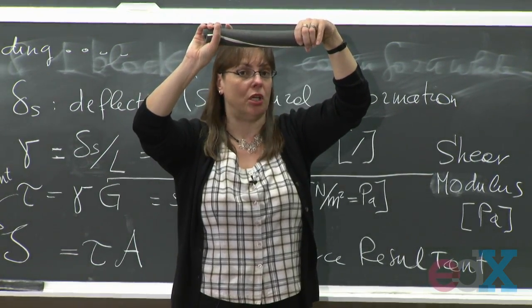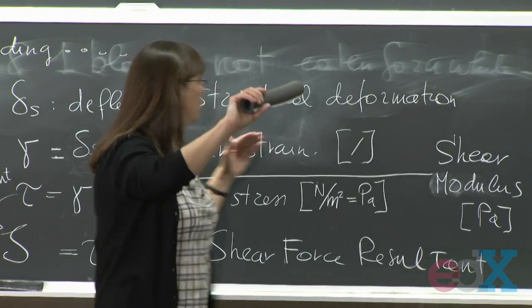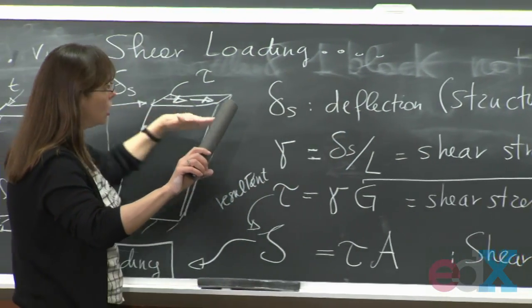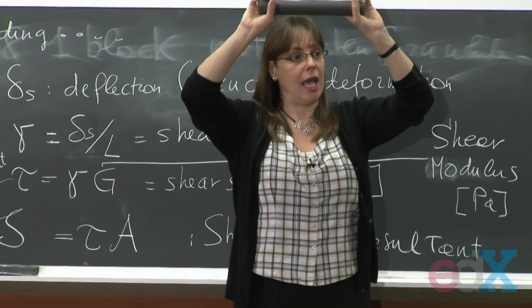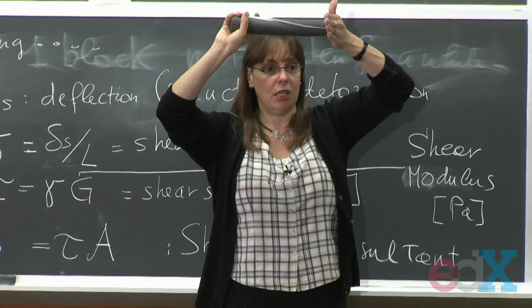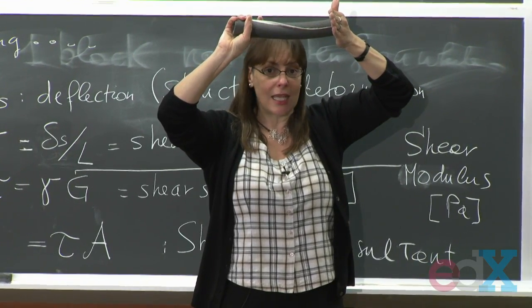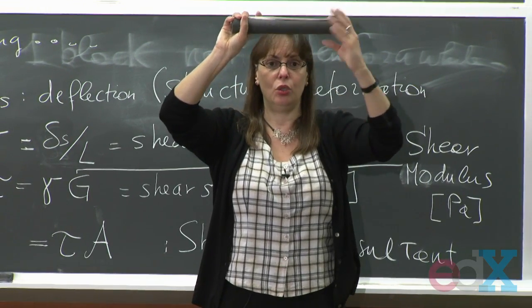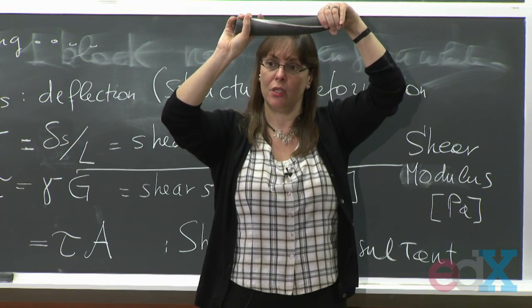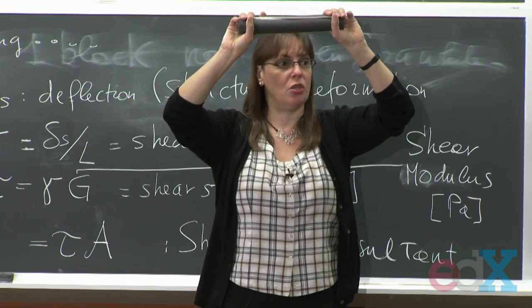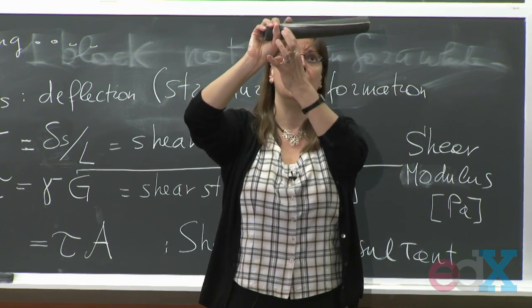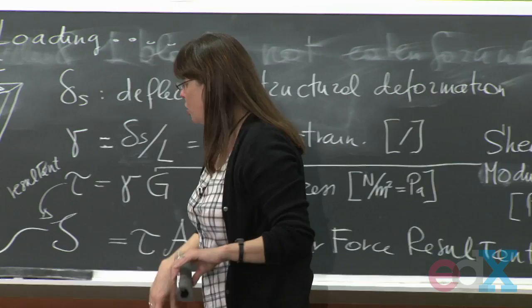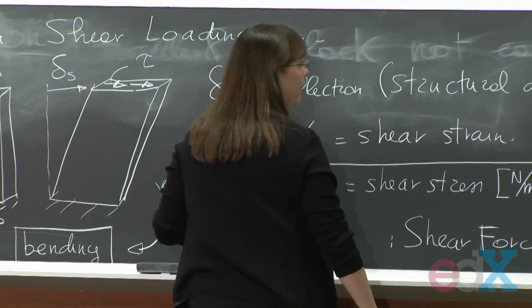It goes in torsion. So I go from this kind of concept of shearing the top of a slab of material to wrapping the slab around and then shearing this side. And the result of it is that the tube gets twisted around. You see the line? It used to be straight. It's not straight anymore. Actually, it wraps around in a straight edge along the pipe.